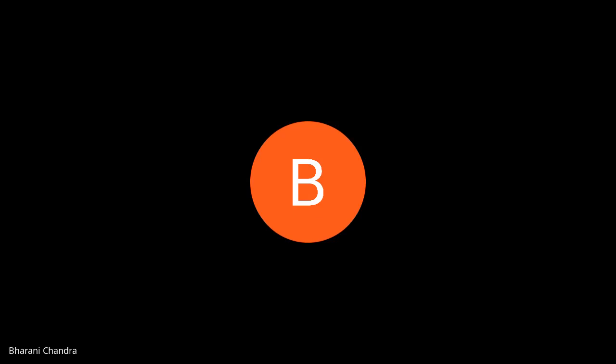At the same time, try to excite the system with various kinds of frequency signals. First of all, you have to see what kind of frequency modes your system will experience. Based upon that, you have to excite the system with the corresponding frequency domain signals, the combination of frequency and time domain signals, chirp signals, and so on, and then you can identify the systems. Yes, it is possible to identify complex systems, not only electrical systems, whatever they could be.